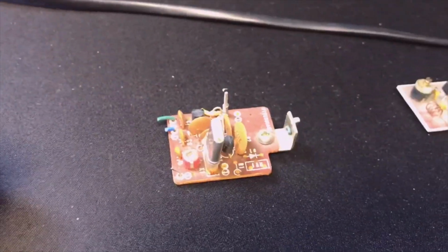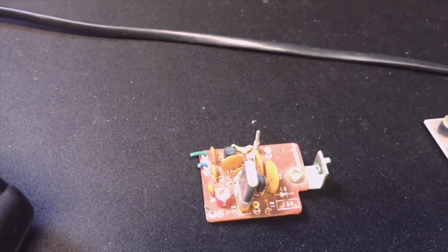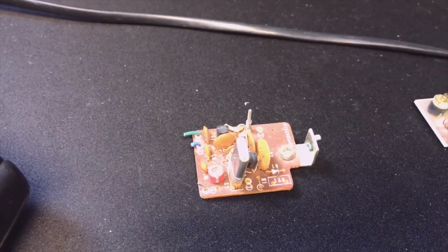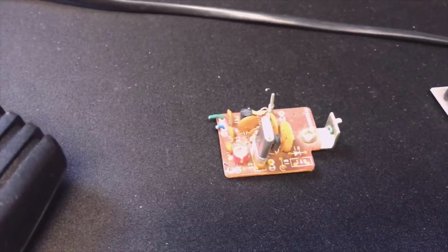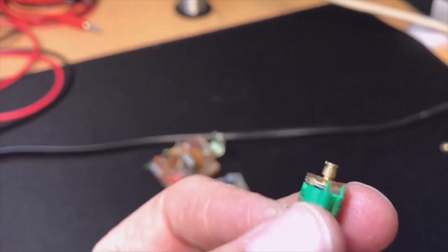People use 2 crystals: the standard is the 10.24, but you can use a 10.245, and then you're almost there, so you just switch the crystals. But usually it's very simple, and you just use one of these trimmers.